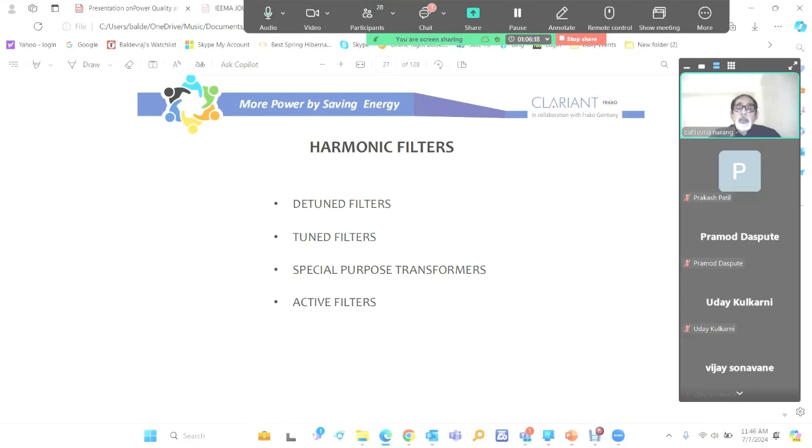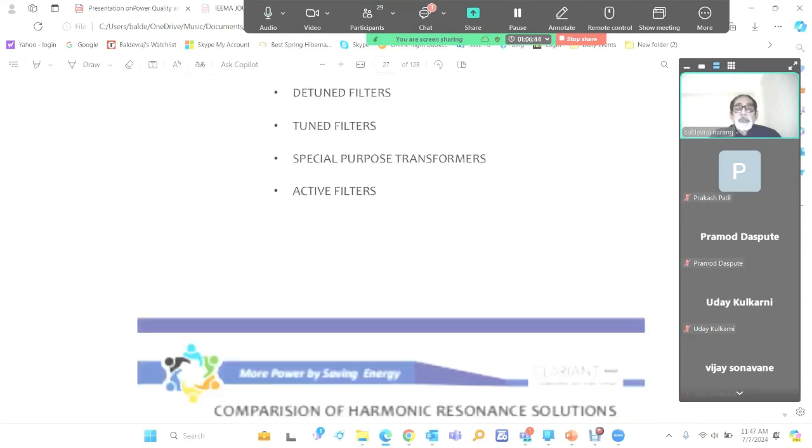It could have many harmonics. The load may be very difficult. So along with passive filters, we have to use active filters also. With active filters, we can generate any harmonic current and cancel out the present harmonics by injecting it 180 degrees out of phase. So we only have to configure the harmonics in the system.